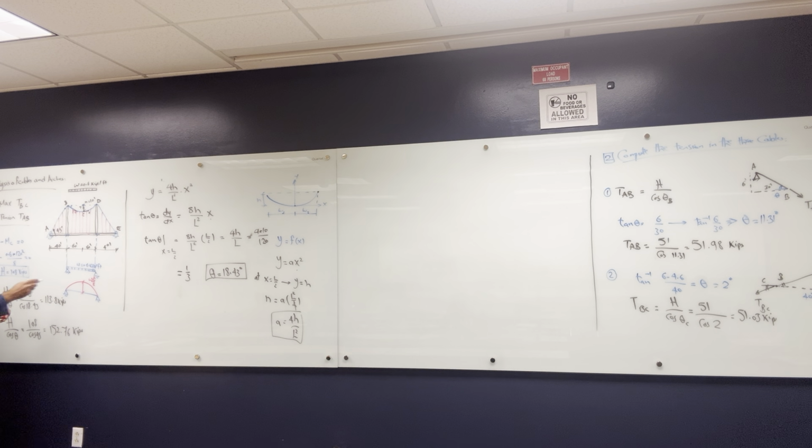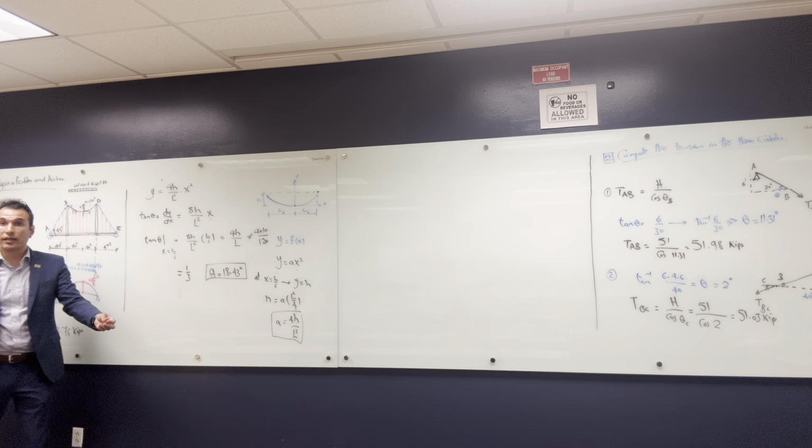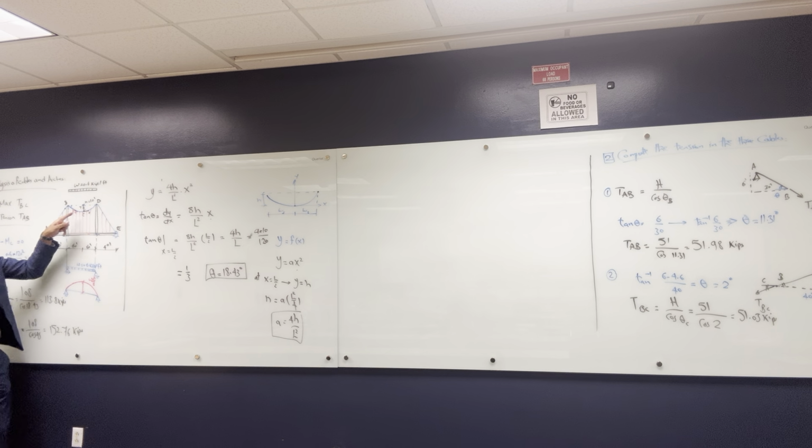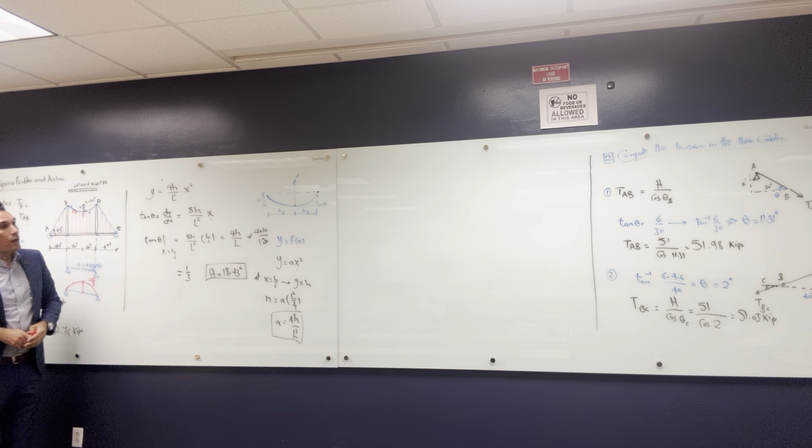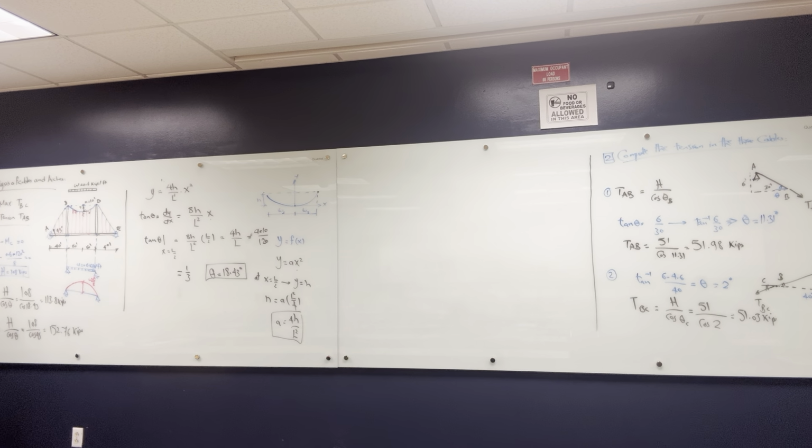So you'll find that the bending moment has small broken lines that are going to make a problem. So either you simplify it as a distributed load, or you can put it as concentrated loads. And then you solve this cable. So when we do this, first we solve the slab. And once we solve the slab, we solve these small cables. And once we solve these small cables, we solve this cable. Okay? All right.